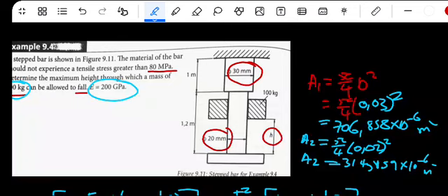For the maximum stress, they say the maximum height, so we have been given the expression. We remember that the greatest stress will occur in the smallest bar. The maximum stress will take place here. This is the maximum stress, and it applies in the small cross section, where the diameter is 20.